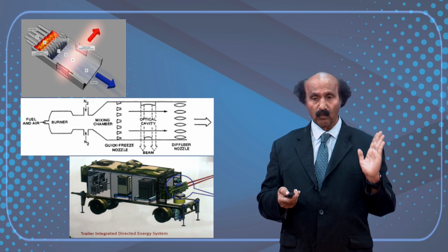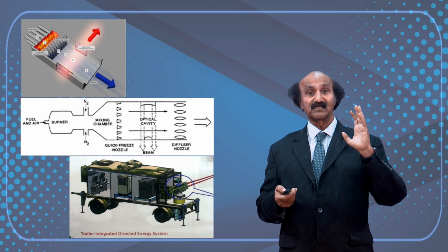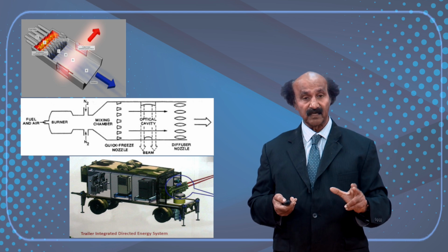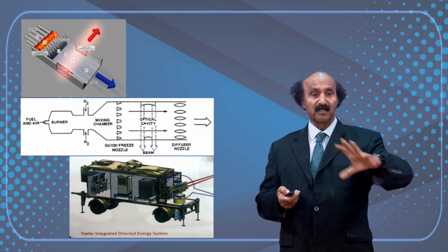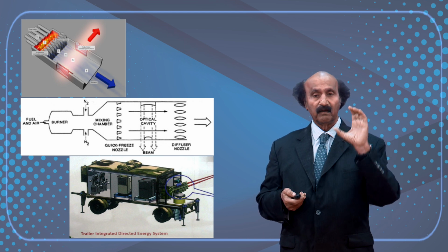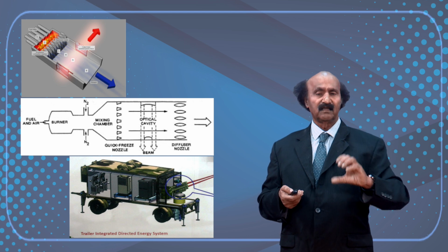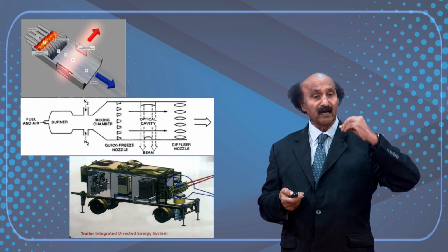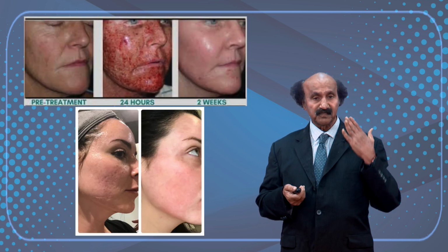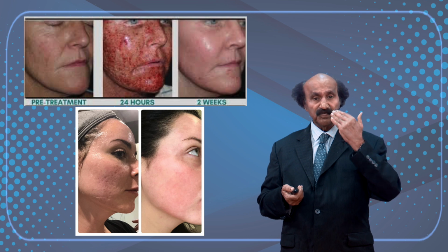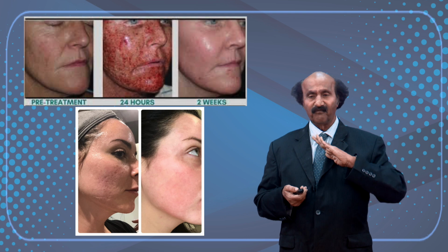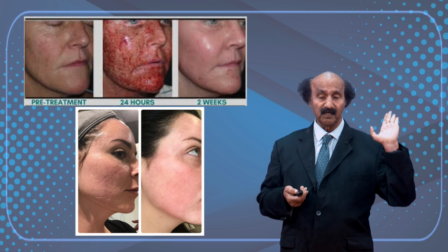What is most common, most successful is the CW laser, continuous wave CW laser, exclusively used for material processing, extremely good. Low power CW laser, low power means below 10 watt, is very good for a variety of medical applications, particularly for all kinds of skin treatment. Any kind of skin treatment you have, if you have lesions and hemangiomas, birthmark, if you have certain tattoo, for all of these the CO2 laser is very, very efficient and it is very common.